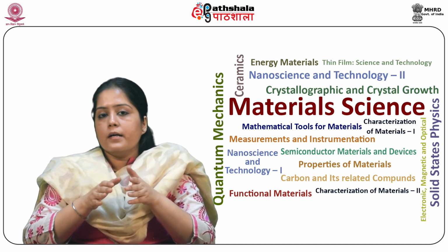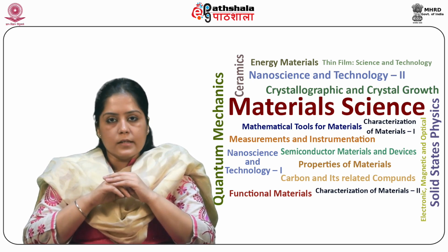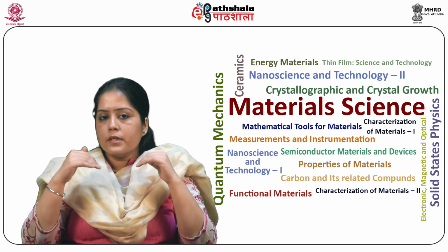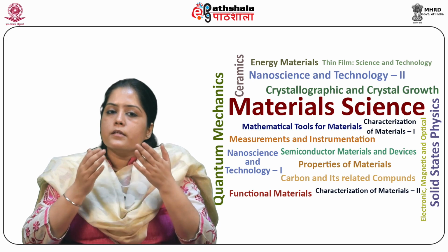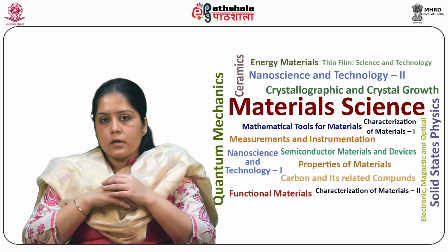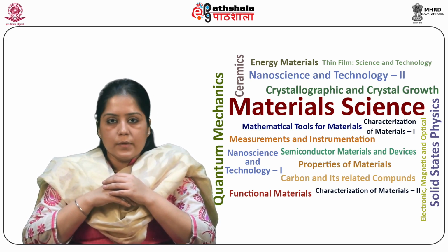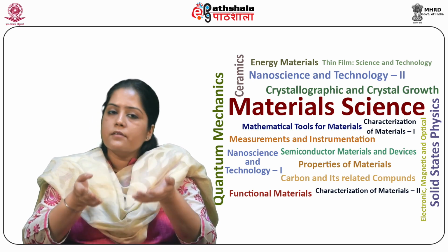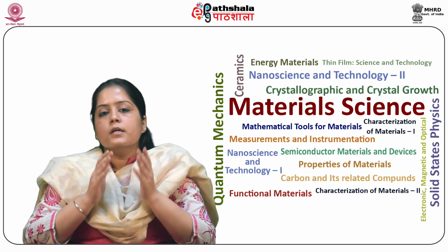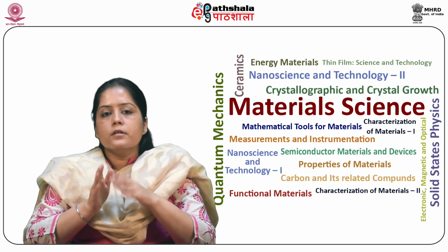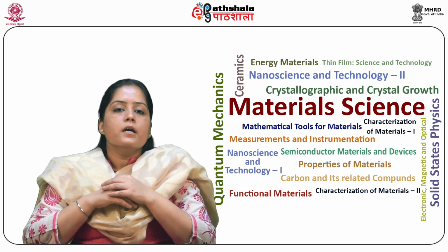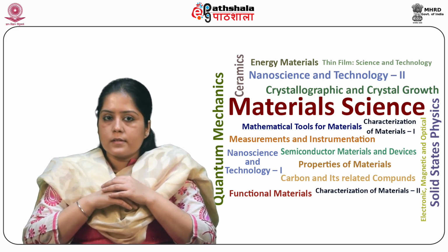The direct band gap of gallium arsenide can absorb sunlight very quickly after it enters. The techniques to deposit gallium arsenide include molecular beam epitaxy MBE, MOCVD, CVD and LPE. Homo, hetero, stacked, multi-junction, tandem junction and PEC are possible in the case of gallium arsenide solar cells.